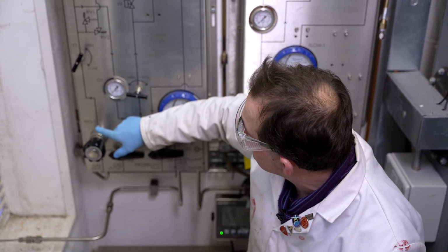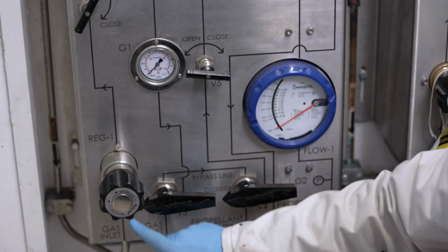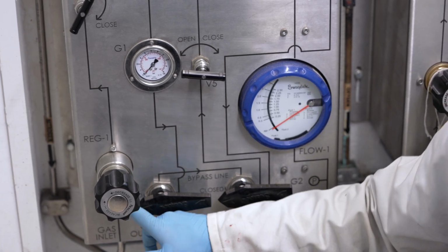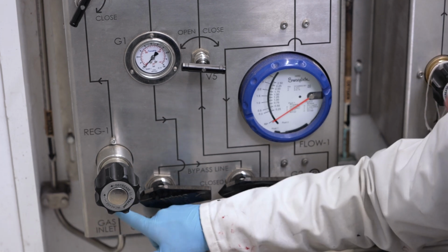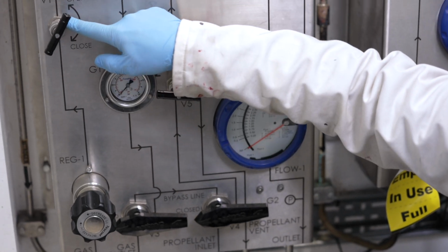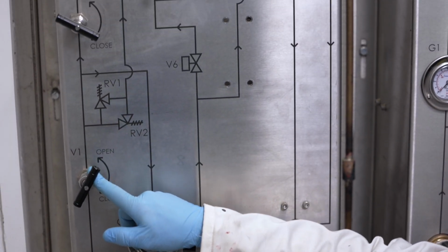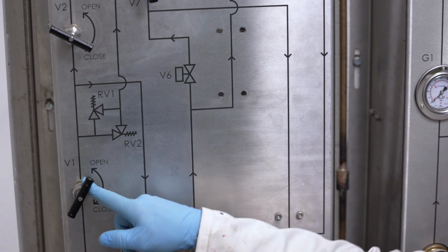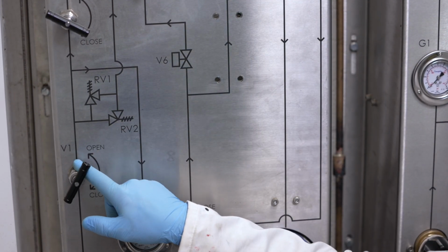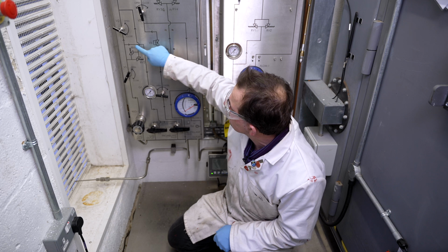At the regulator, the pressure gets regulated down and then will go through our system. Now, although not shown on this particular flow diagram, there's actually a filter before it goes into the regulator. So it comes through into a filter, into our pressure regulator, through our first valve. Notice that all of these valves are not ball valves, these are all metered valves, okay, which allows us to be a bit more flexible with what types of propellants we put through this system. The working fluid or gas will come through our system.